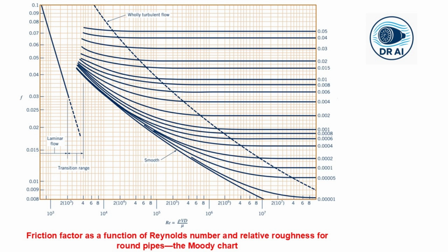First, if we look on the left-hand side in the laminar region, where the Reynolds number is less than 2100, you see a single straight line. That's for f equals 64 over Reynolds number. It is independent of roughness. This matches our theoretical result as described earlier.